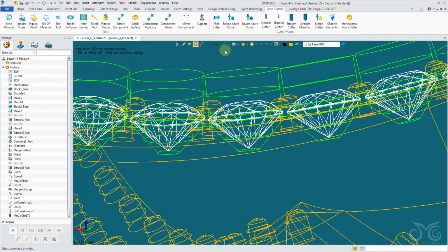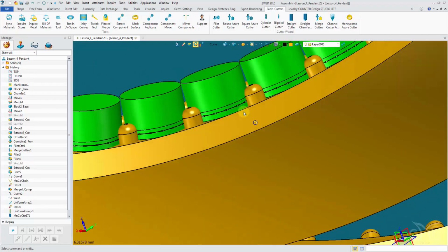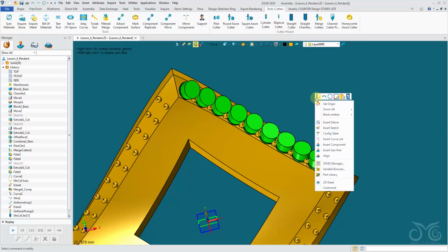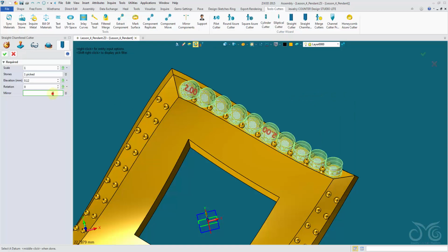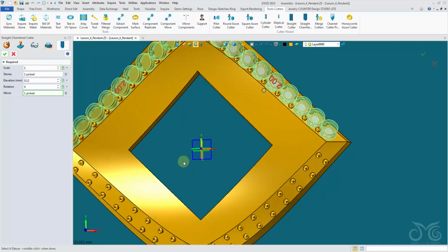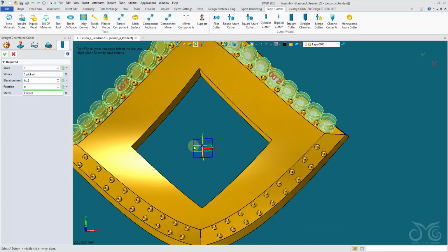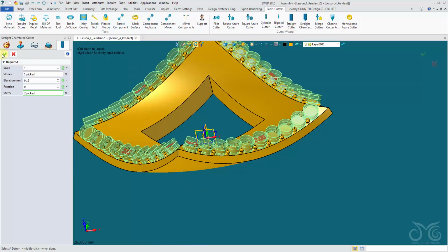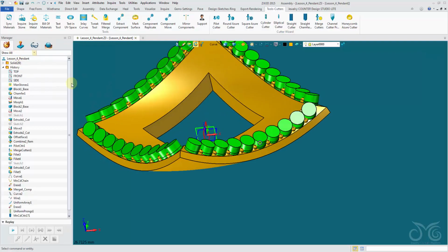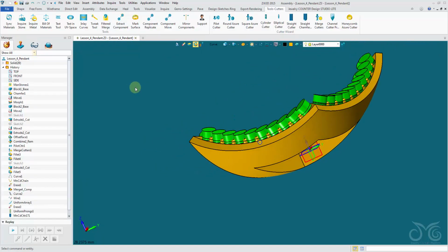Exit out of my tweak. Here are the cutters. Okay, I made the mistake again of not mirroring my cutters like I did the prongs. So let's do the same for them. Confirm the operation. Cancel out of the tweak, and there are our cutters.